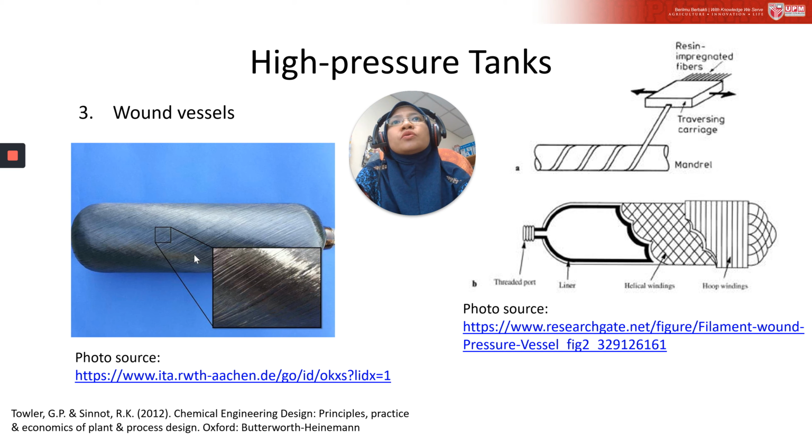All right. So winding on the wire under tension places the cylinder under compression. For high pressure vessels, special interlocking strips are used. So some of the design here has interlocking. The strip may be wound on hot to increase the pre-stressing. Okay, so you may refer to other references for detail on this.